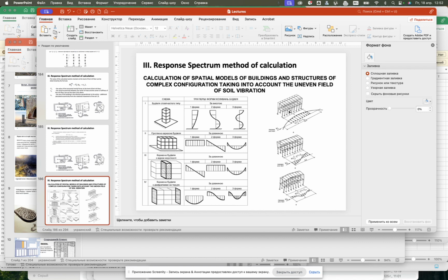For a simple building, everything will be okay: in plane there will be the same displacement of these parts of the slabs. But when we are talking about a long building, we will get additional effects connected with the length of the seismic wave. These effects can also be taken into account by the spectral method with additional coefficients. Here are those methods of calculation.